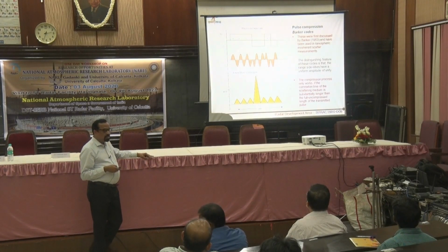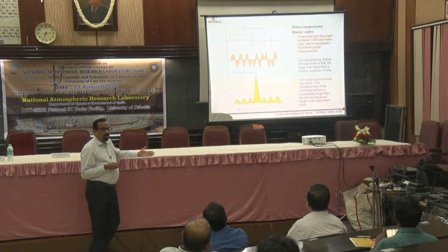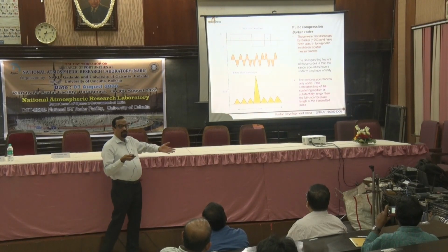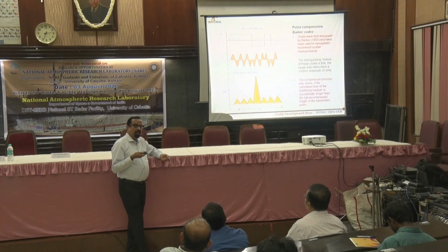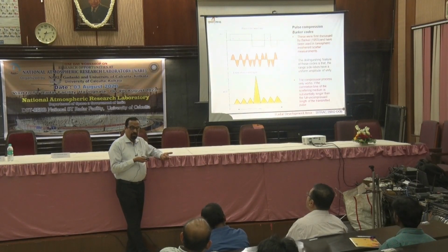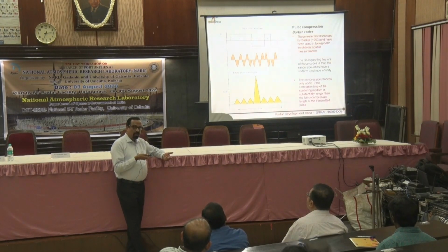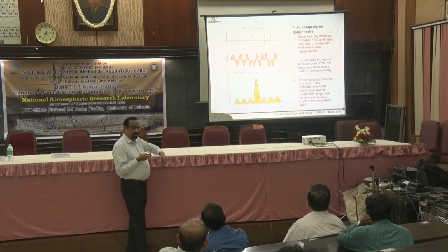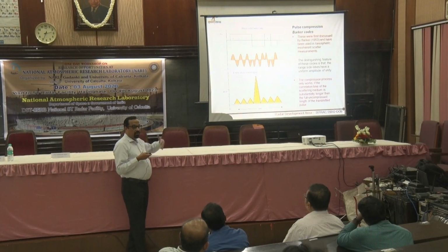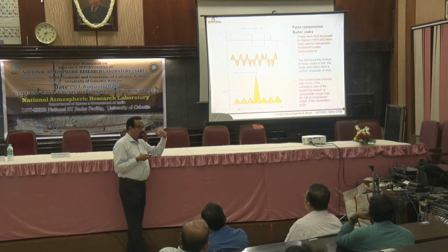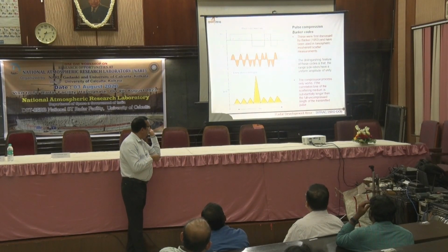For pulse compression, you can see a glimpse of it, because probably somebody has learned or heard about Barker codes or some compression techniques. Why it is important: anything which you create basically convolves with the medium that you are going to face. Convolution is not always straightforward; it will always create small babies around it. That is what is happening here also. When you send a small code, with a shape like the rectangular pulse you are seeing, and you correlate or convolve with the medium and want to decode it back, that signal will be shaped like the last one you are seeing. That means you do not ideally get a single line.